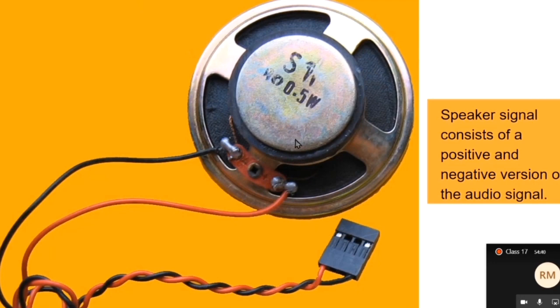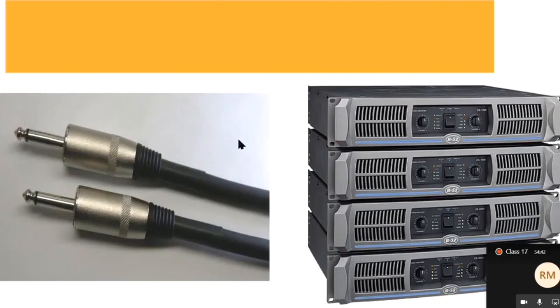Like I've done, as a kid, trying to figure out cables. I had accidentally plugged a speaker cable into my guitar and was dumbfounded by the lack of results. It was noisy. I put the cable in and then took it out halfway, and then I could kind of hear it, but then it cut out. I was like, what is wrong with this cable? So usually what you've got to do is see this portion of the cable right by the plug. It'll typically say speaker or instrument.